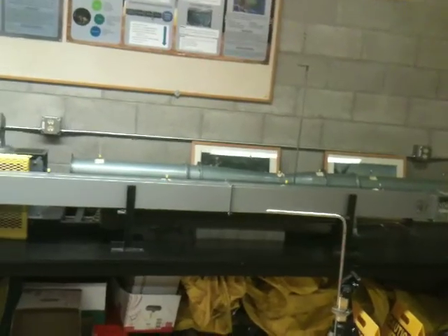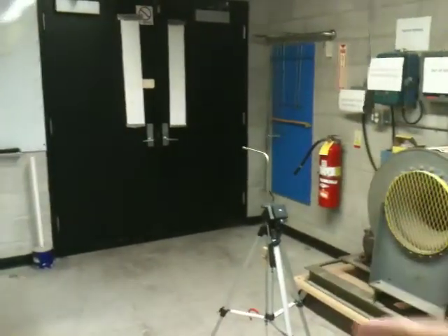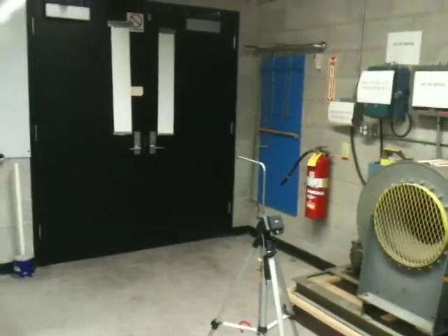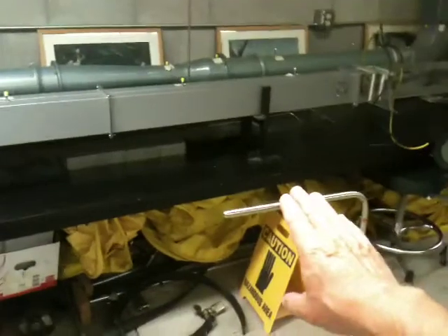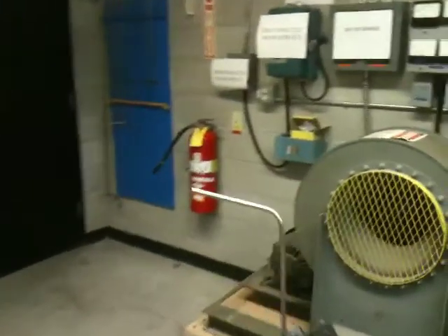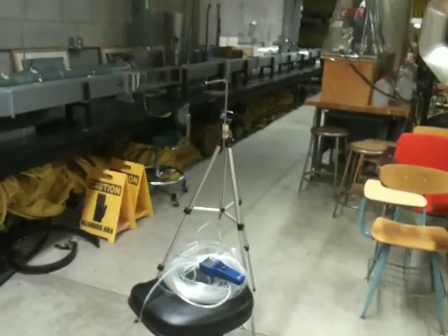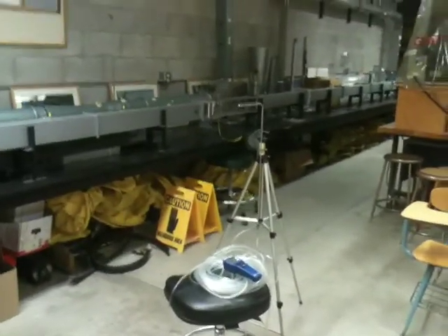So both of these are facing into the flow, and we'll just record a measurement, and then what we will do is we'll move the downstream pitot tube past the upstream pitot tube to the next measuring station. We will reverse the connections on the manometer, so this one will now become the upstream or positive pitot tube. This one will be the downstream or negative pitot tube, and we repeat the process going around the loop. Okay, so fairly simple, and with that background, let's go take some measurements.